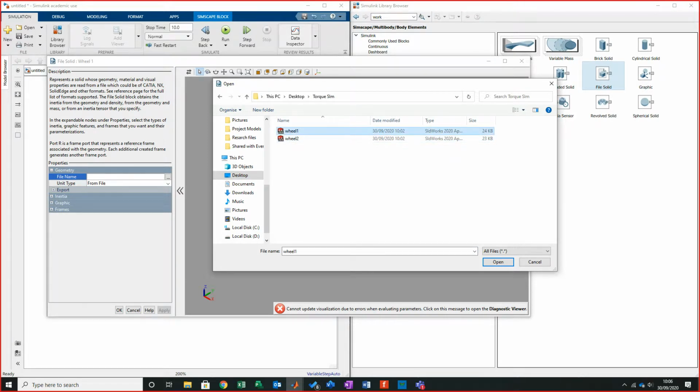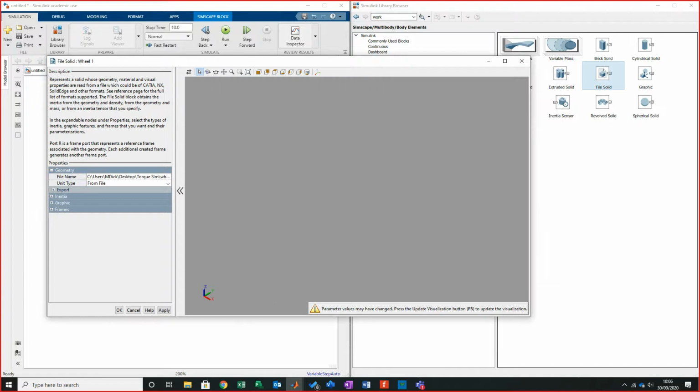This system prefers to read from step files. Step files, there's been lots of translational arguments for years. What is the best way forwards? IGES was on top, then funnily enough STL, stereolithography files, were on top, and then step files. And step had one particular point, and the new one, 214 step files, can actually record lots of extra data in it as well. So there's an awful lot of stuff going on in that. So what this will read is step files. And click open. Now you see there, parameters variables, so press F5.